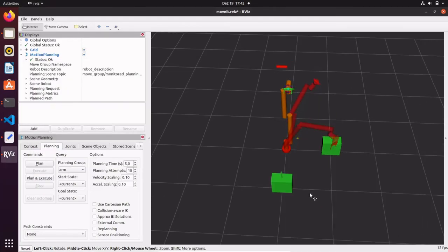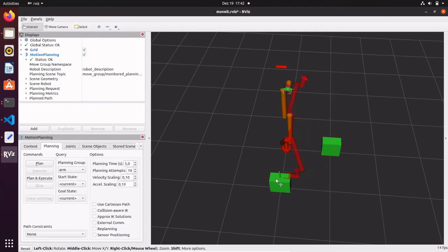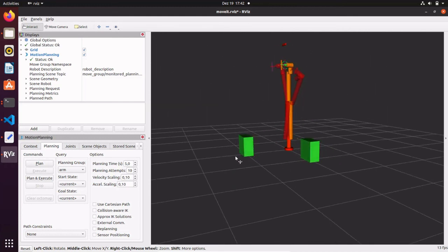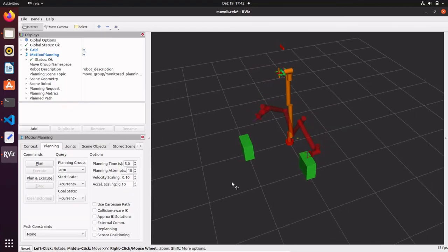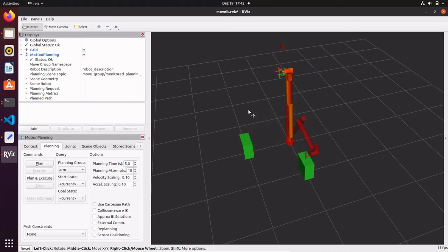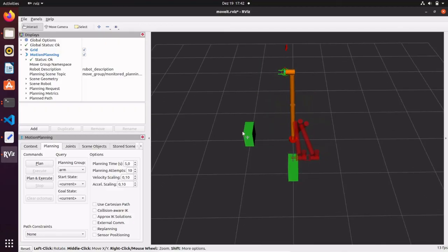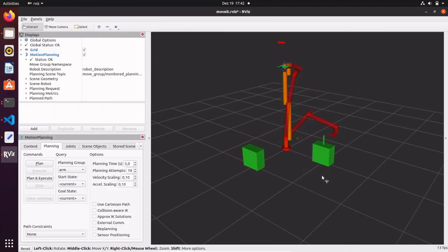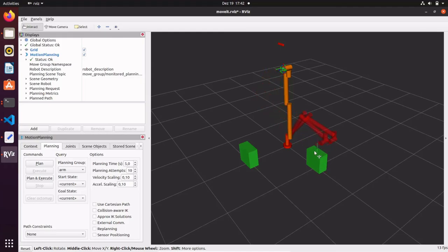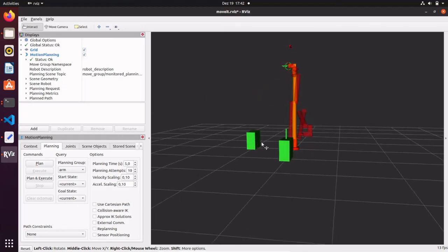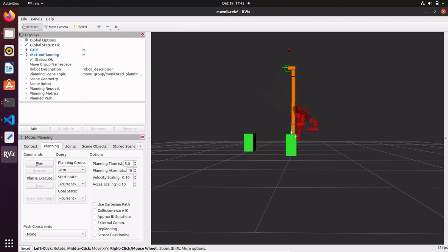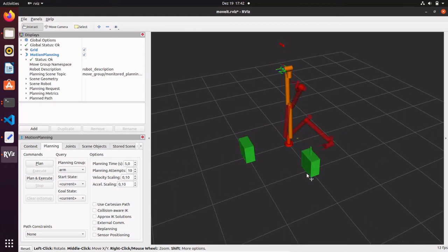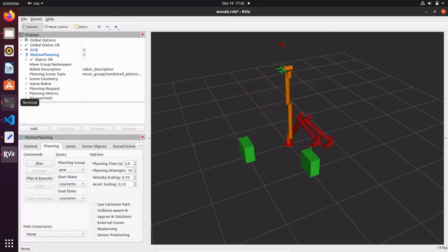Now it's approaching from the opposite side. Okay, it's picking, the object is turning purple, and then it's going to the place position. Okay, this is acting, let's say, weird. It's not necessary that the cobot makes this turn, it should be just straight. But I'm sure that if we run it again, it will be much more straightforward. The point here is that now you can see that the motion planning is different, and we needed to update the retreat to the negative x, because we have changed the position of the TCP in the picking position.